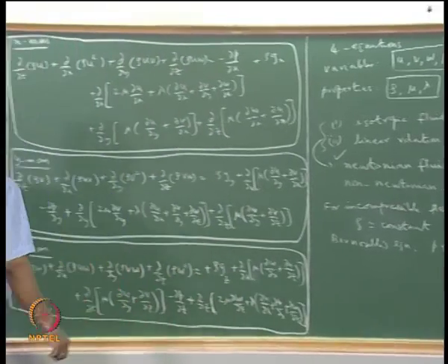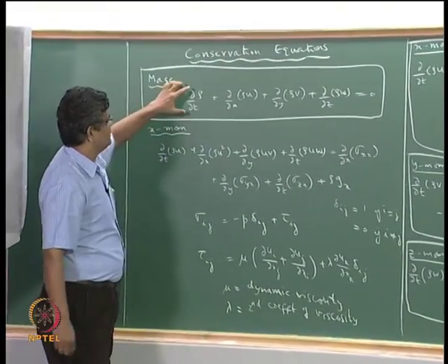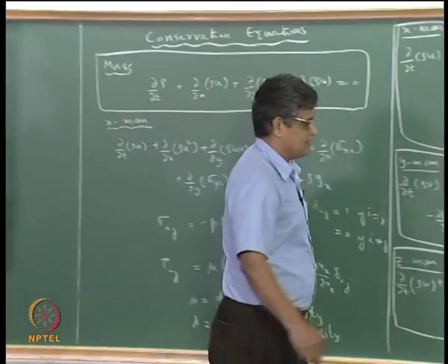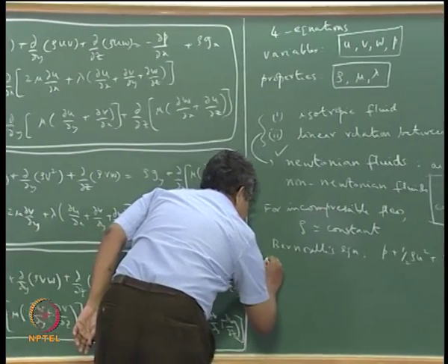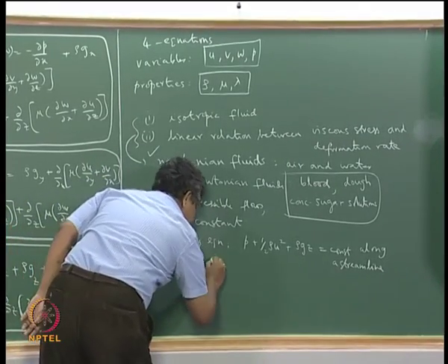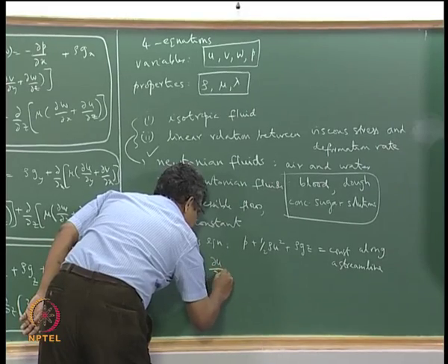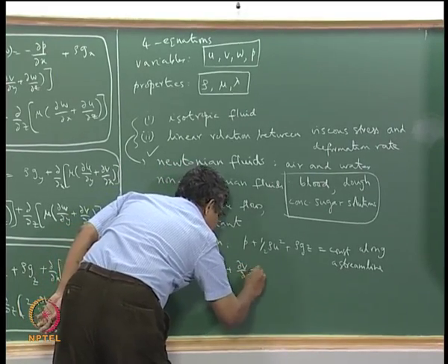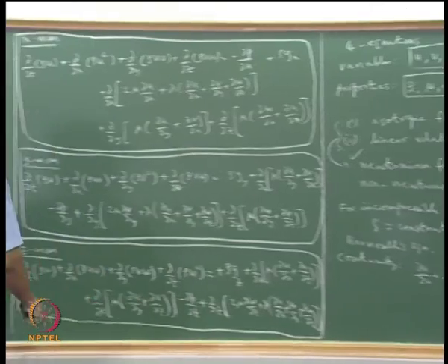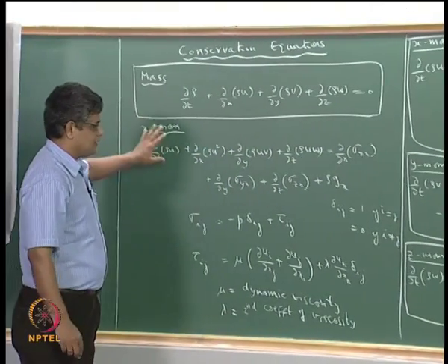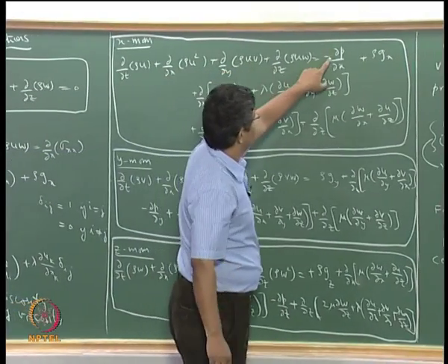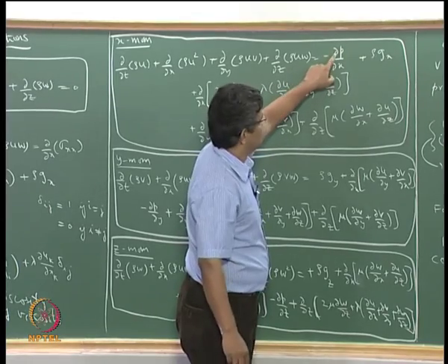So when you come to the continuity equation, this term becomes 0, rho is constant, so it can be taken out of the domain, and we can write the continuity equation reduces to ∂u/∂x plus ∂v/∂y plus ∂w/∂z equal to 0, and in the x momentum equation also here rho can be taken out and it can be put here as 1 by rho ∂p/∂x.